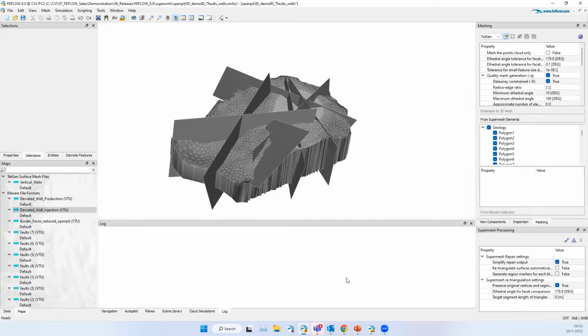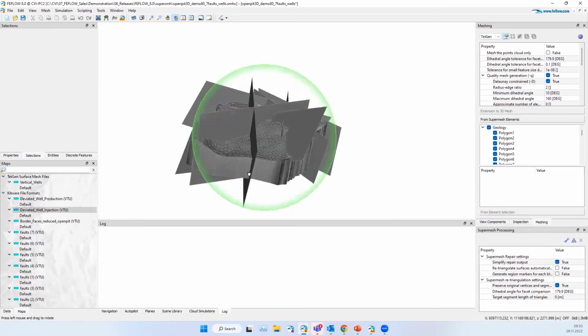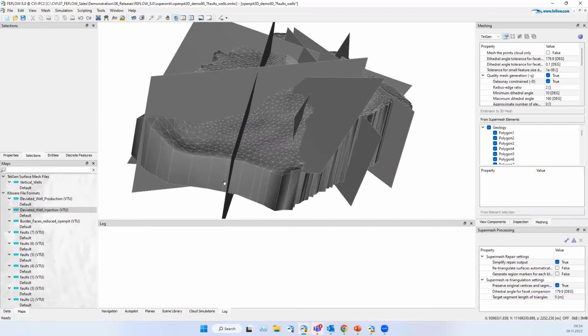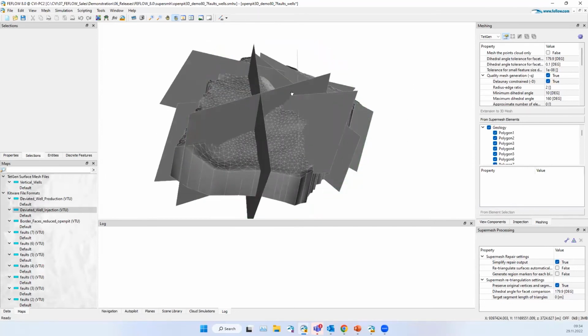We are now intensely continuing to work on more tools. There are a number of options. The two major options: you repair. Repair is the first button. Repair surfaces: basically, we look where the conflict exists and then repair the connectivity between the intersections. So if I take this plane, we'll repair it here, and we'll also discard surfaces outside. That's how we decided to implement this inside FEFLOW.